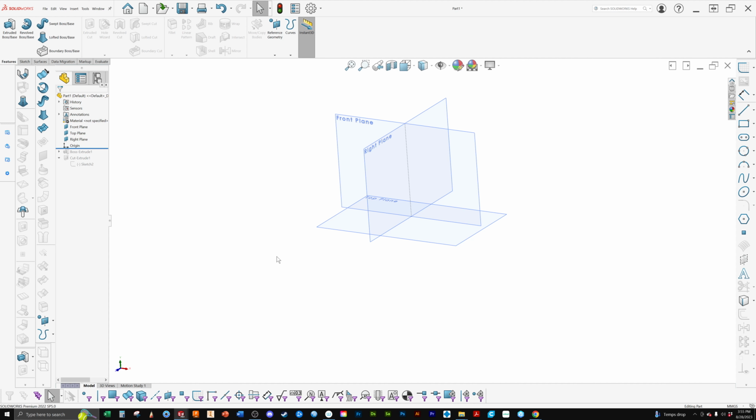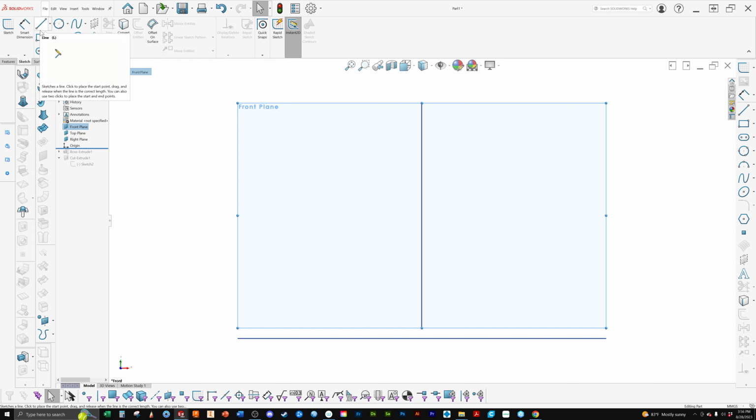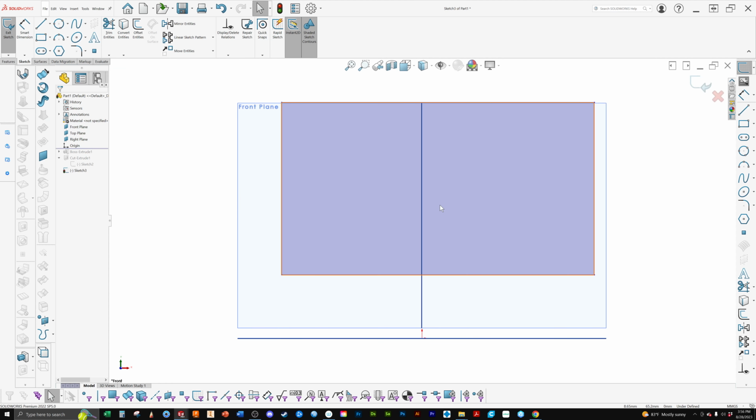And it's one of those things, it compounds. So if there's a small error in your sketch, when you do your command off of that 2D sketch, it becomes more apparent. And as you keep building your model, it gets worse and worse. Something as simple as if I'm building a box and I think that looks like it's centered.